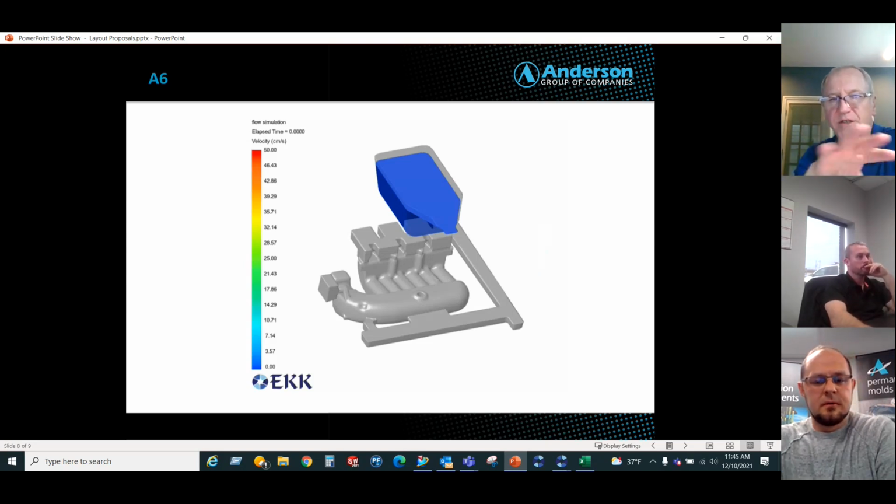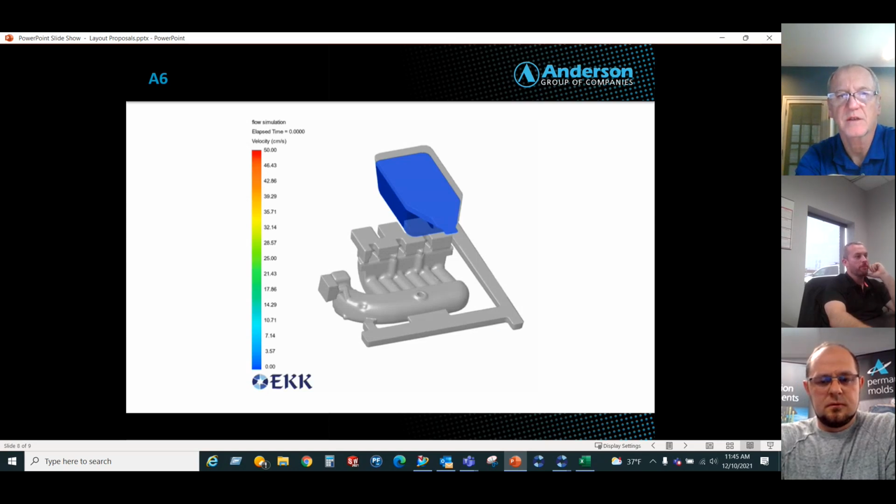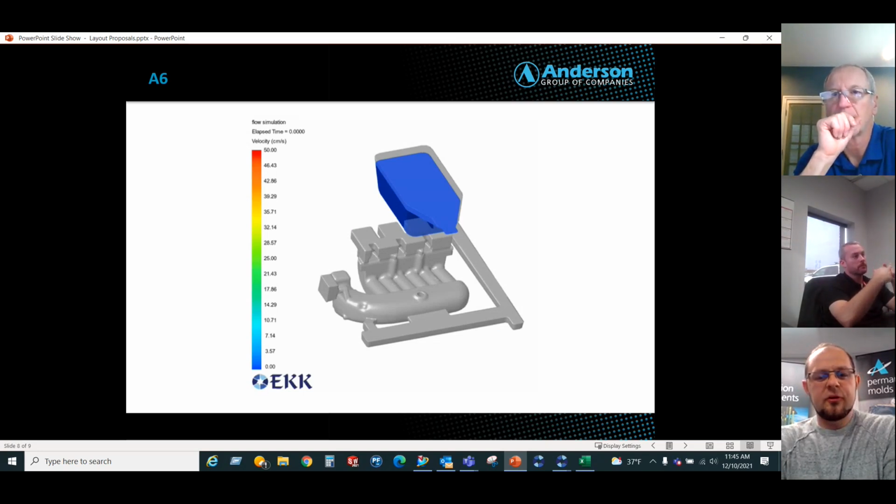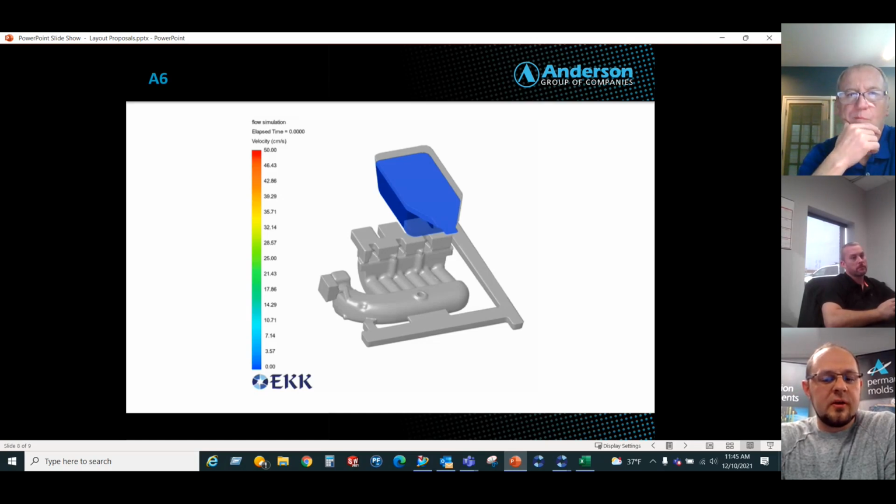So what we're looking at here is different potential gating designs, mostly. If I've got terminology correct, I'm not seeing any risers. Yes, there are risers here, but typically it's casting orientation where it really comes down to which side is at the bottom in the drag half, which side is at the top half, the cope half, and different customers have different preferences. But it's the number of runners. Sometimes it's a double runner, sometimes it's a single runner system. Gate sizes,